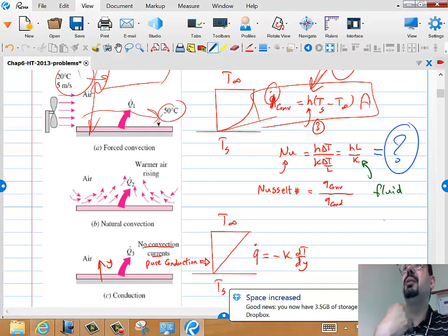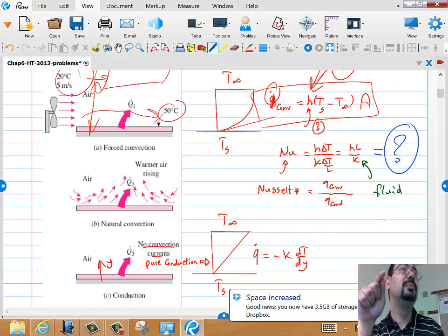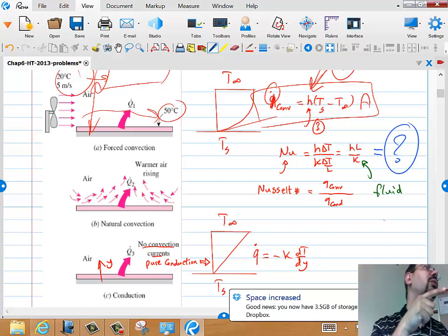There is no extra. But if we turn on the fan, if we let gravity take the air and rise and bring fresh air, we expect the Nusselt number to be greater than 1. Jay is saying it will be greater than 1. So if you are in the exam and you calculate a Nusselt number less than 1, know something is wrong. The Nusselt number for any convection problem needs to be 1 or higher, because we are boosting the mechanism that transfers heat.